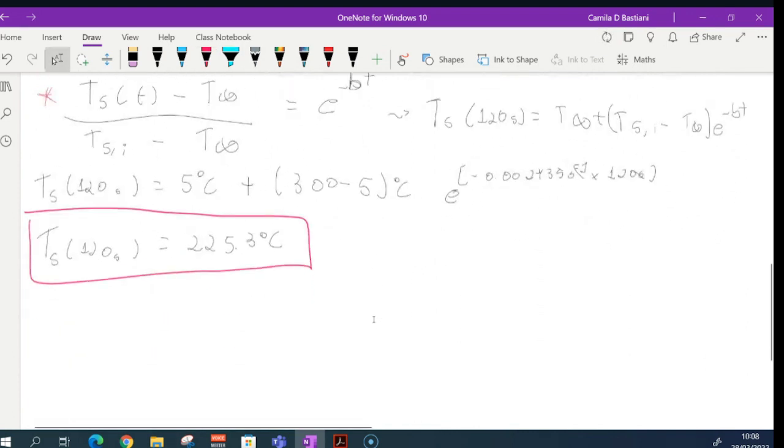Well, we are talking here about my metal plate, and I'm talking about convection as well. Remember that when we are talking about my no-slip condition, I can say that my heat transfer due to convection in the first layer in the plate is the same amount of heat transfer that I have due to the convection up here, is the same amount of conduction in this first layer because my first layer has a velocity equal to 0.